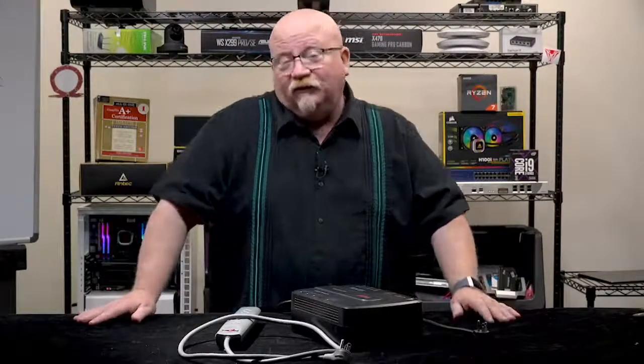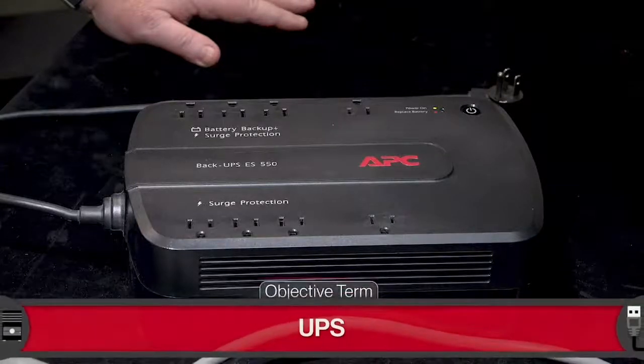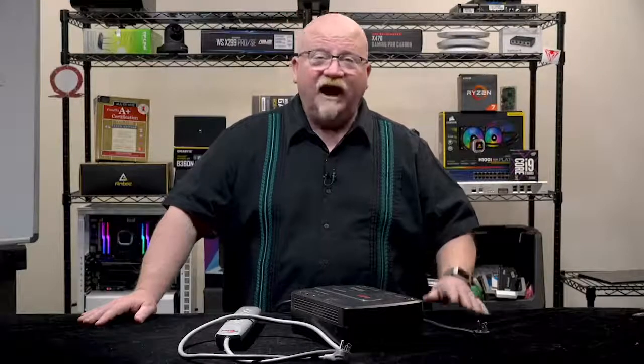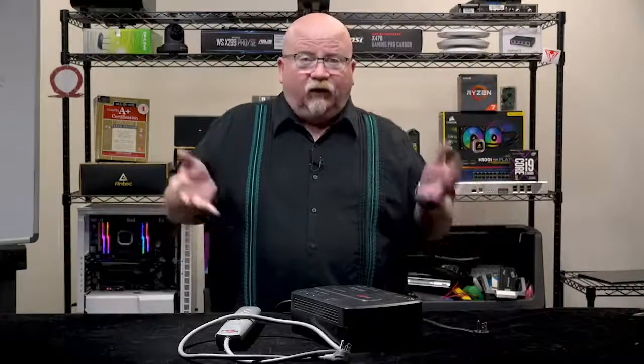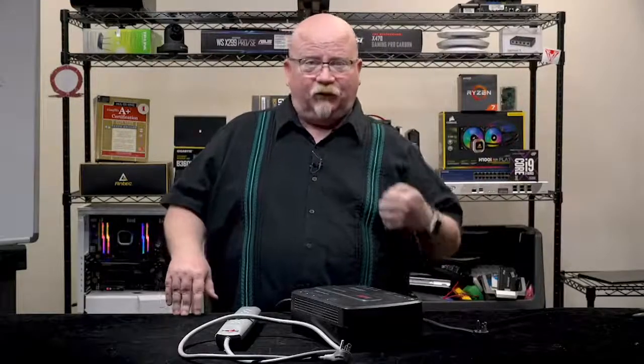Now, if you really want to do things right, what you want to go to is a beastie like this. What you're looking at here is an uninterruptible power supply, or UPS. UPSs protect not only from spikes and surges, they help protect you from sags and brownouts. Now think about this for a minute. How would it do that? In order to do that, it would have to make electricity. If things don't give you enough, somebody's going to have to pour some electricity in.